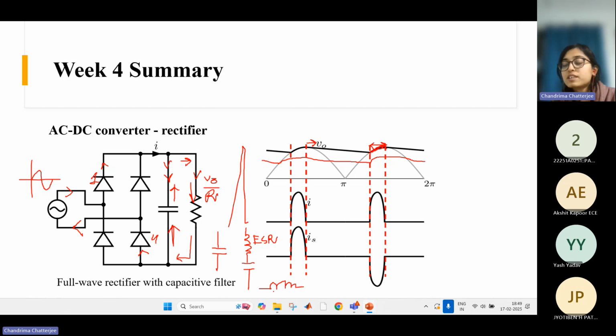But when you make an inductor, you have to give certain turns around a core, winding some wires. Those wires will have their own resistance. So the practical model will be a resistance in series with an inductor, and again there will be some power dissipation in this resistance. So practically, there is no element where there is zero loss.